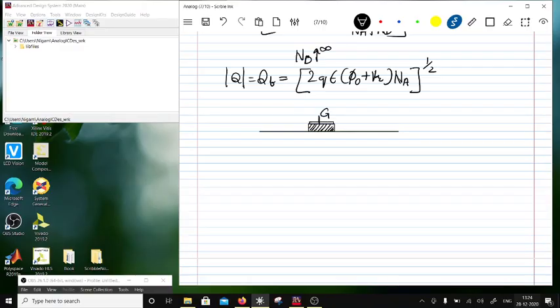So once you have a gate terminal, what you do is you can implant the wafer, which to start with is P minus, right? So now you can implant regions around the gate, and the channel would be formed by the gate itself. This kind of process is known as a self-aligned process.